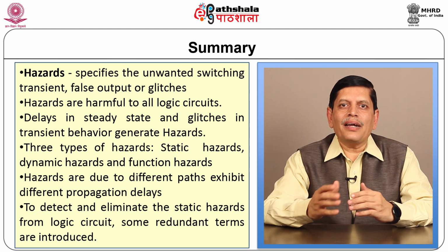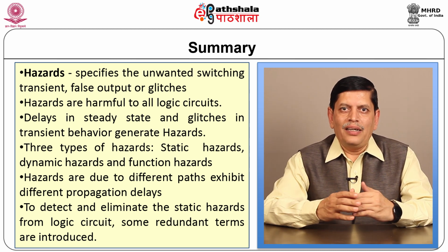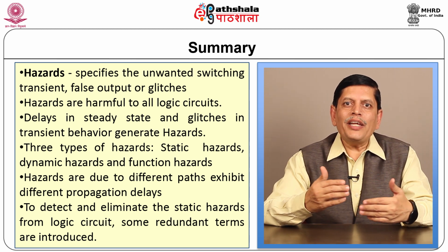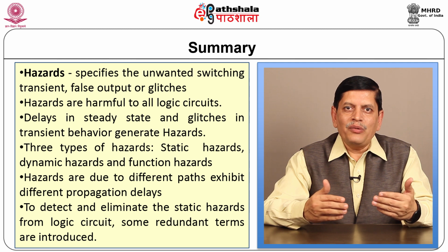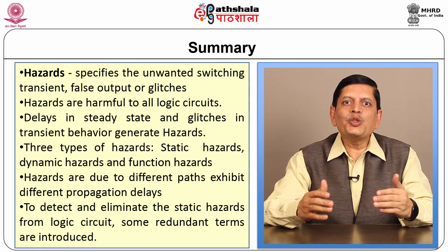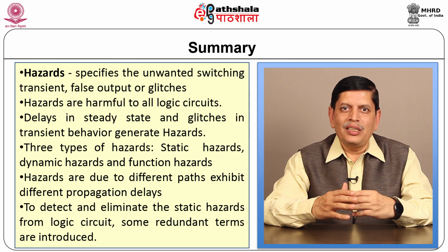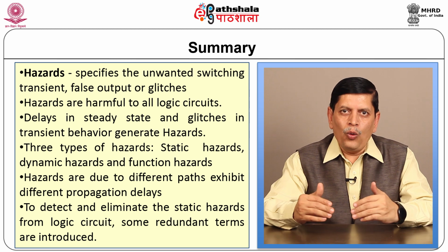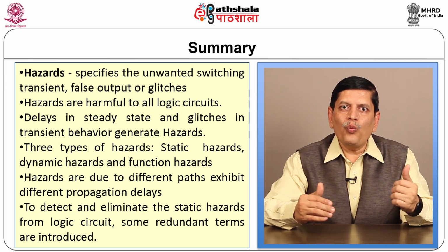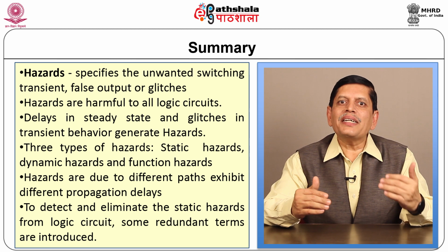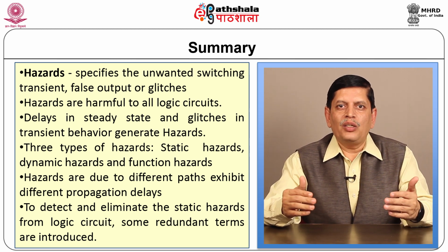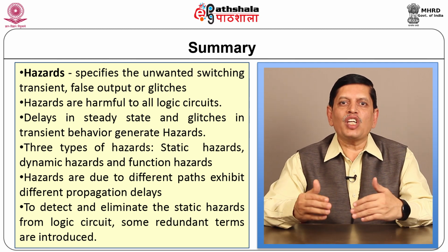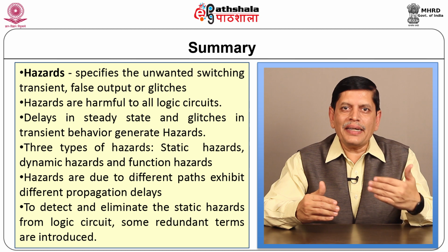Similarly, there is a third hazard that is present, that is a function hazard. This function hazard is the hazard wherein there is more than one input changing with respect to time. These are usually non-solvable hazards. The best way to avoid this function hazard is not to allow more than one input to change. But in real situations it is impossible. So, function hazards are really difficult to eliminate, but static and dynamic hazards can be detected and then eliminated by using some special technique.